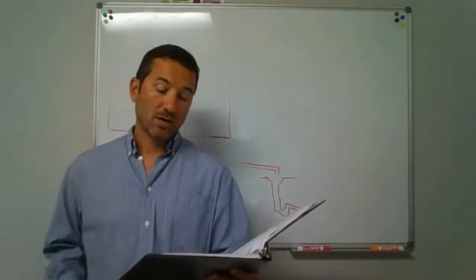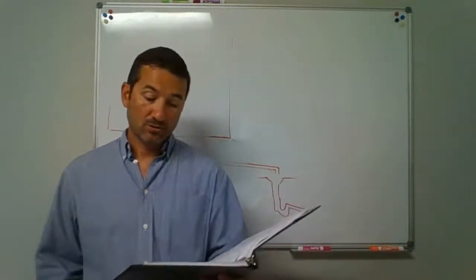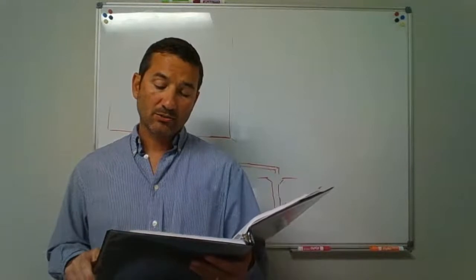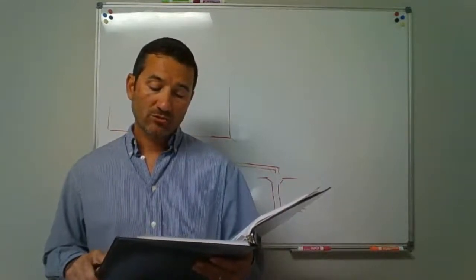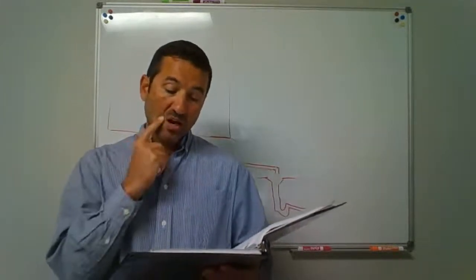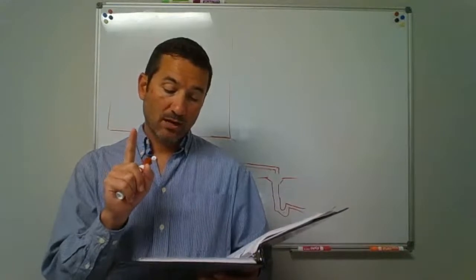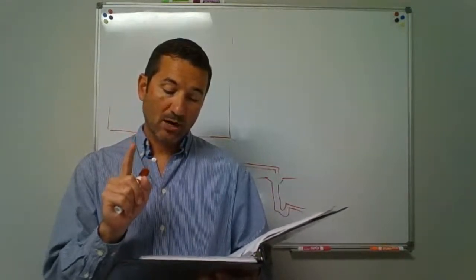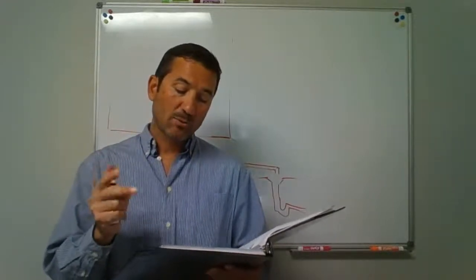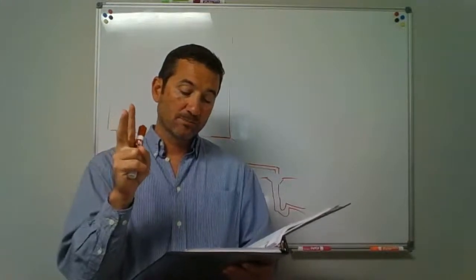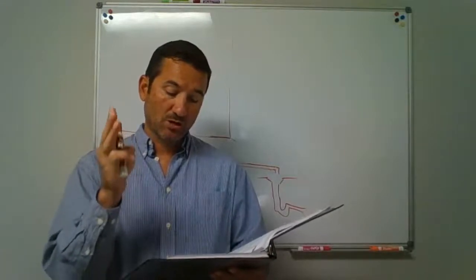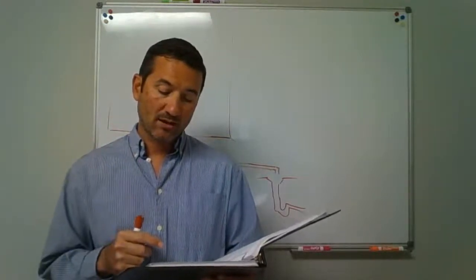So here are some rules about your dishwashing machine at the house. Domestic dishwashing machines shall discharge indirectly through an air gap or air break into a waste receptor in accordance with section 802.2. So there's one possibility. Connecting discharge indirectly through an air gap or air break into a waste receptor. It shall discharge into a Y branch fitting on the tailpiece of the kitchen sink. There's a second possibility. Or the dishwasher connection of the food waste disposer. There's a third possibility as far as where that could connect to.